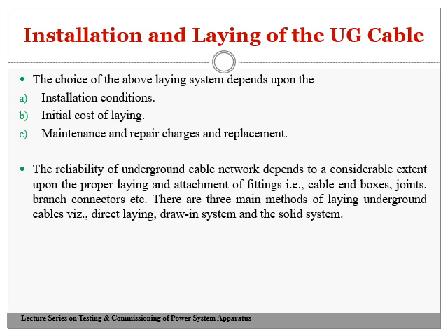The choice of the above laying systems depends upon the installation condition, the initial cost of laying, the maintenance and repair charges, and replacement. That is, the choice of laying depends upon the installation condition, the place where the cable is to be laid. The second one is the cost involved. If the cable capacity is very small, installing racks for the laying is not economically viable.